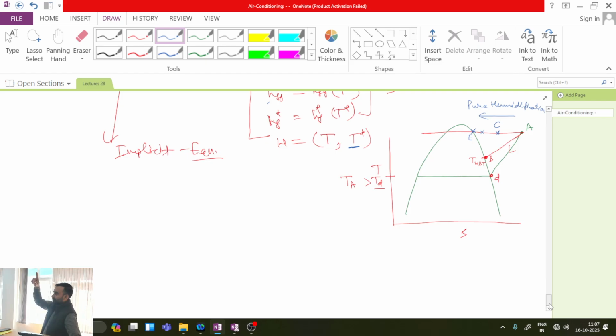In Mollier diagram, a plot between specific enthalpy and specific entropy is called the Mollier diagram, and that contains all the data like constant pressure lines, constant temperature lines, and of course the abscissa and ordinate themselves are entropy and enthalpy. Okay. So likewise, from the single chart I can determine the properties at all the states: compressed state, superheated state or saturated states. Okay. So similarly here also